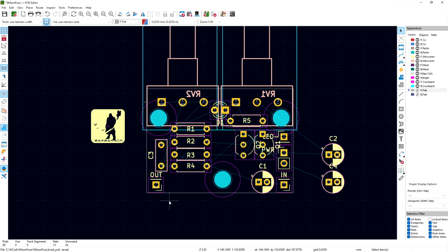But most of the time, like for pedals, it should be okay as long as we don't do something crazy like route things all the way around and make a big antenna and then pick up all sorts of things. But we are in the enclosure, so that helps. Again, I think we gotta keep all the connections as short as possible.